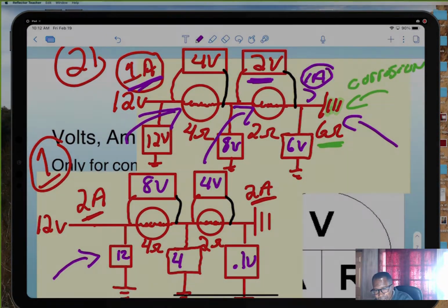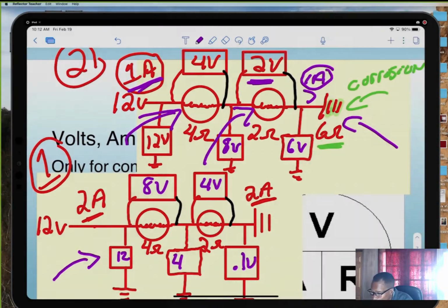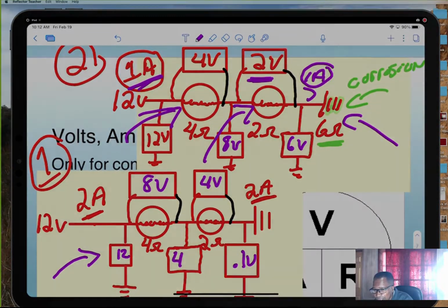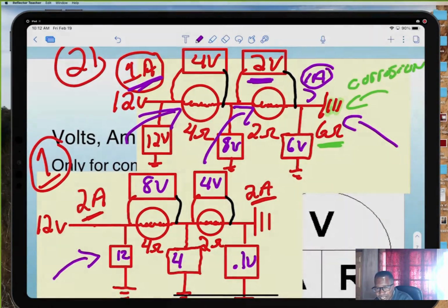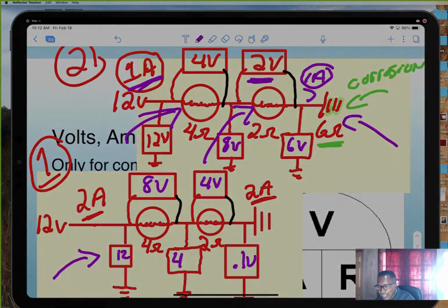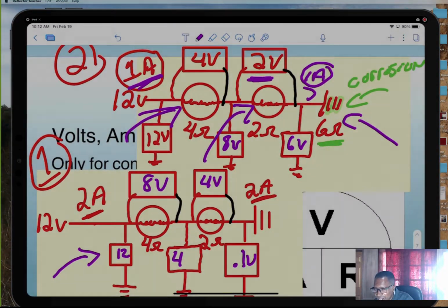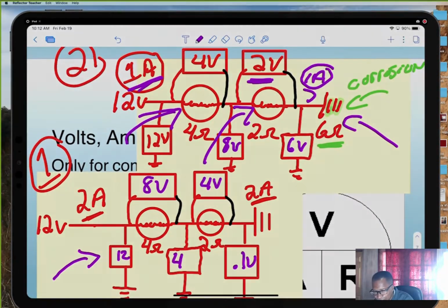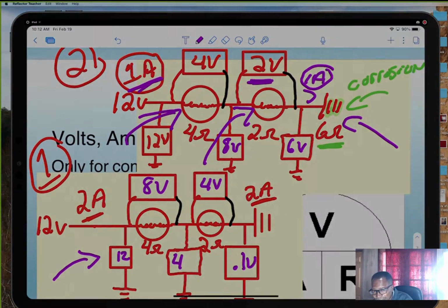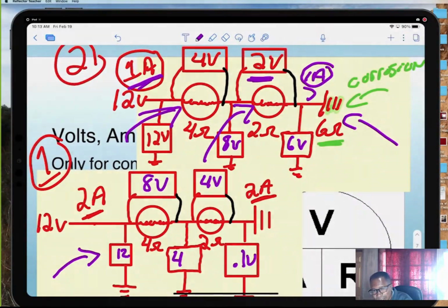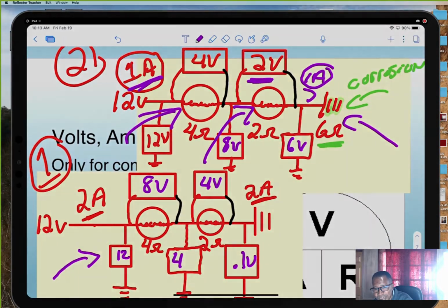Now that could also be a loose connection, right? Yes, it can. You're very right. It could be a loose connection, a frayed connection, corrosion, or a pin pushed not all the way in, just barely touching. Anything that causes resistance or bad contact, that can happen. And like I said earlier, it's hard to find resistance unless it's obviously blatant in your face. So a voltage check, like we just did, will show you the resistance. That 6 volts on the ground side proves there's a resistance on the ground side.